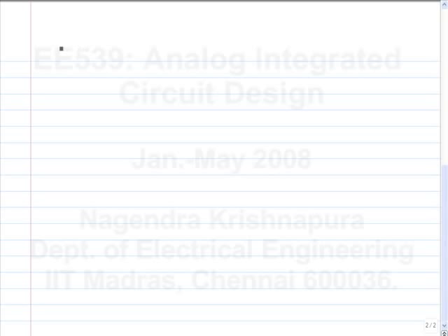Now, all of you are familiar with the square law of the MOSFET. Okay. So in this case, in keeping with the bipolar transistor tradition, you identify one of the terminals as the source. But this model works only if this is the lower potential terminal. Okay. If you do the opposite thing, it won't work. Right. And that is denoted by this arrow typically. And it refers to the current between the drain and source. That is current that flows from the drain to the source through the device.